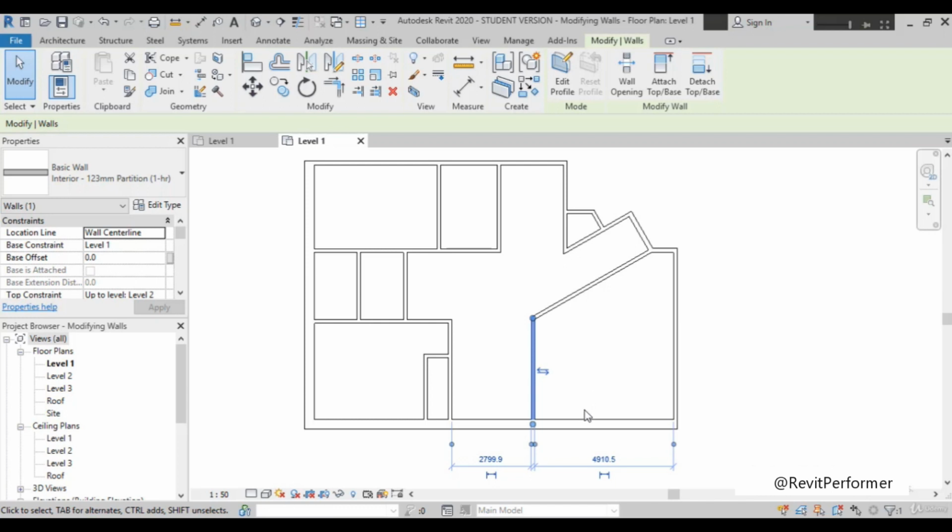the temporary dimensions command, in which you can put the value, so it will be more valuable for you. In my previous lecture I told you how important temporary dimensions are. Sometimes when you use this command, you have to notice how we can manage the tools according to our work, so it goes very fast and very precise. Here I know the value of this. I can use 3750 and press enter, so it will shift very properly.